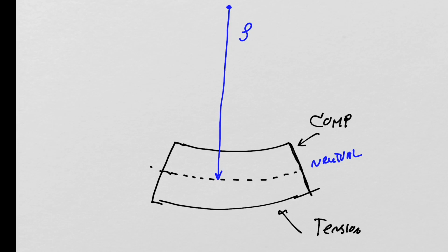And we are going to consider another line that is not the neutral line. I'll put it in red here. And that's this particular fiber of the string. The string has a little fiber here, and that fiber is going to be a distance z above the neutral line. So we're making this sort of mathematical model of the internal structure of a string.